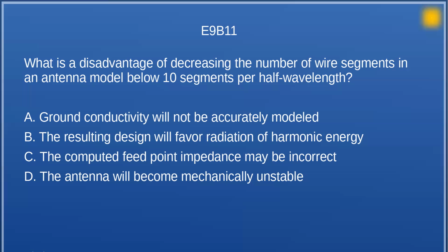Ideally, you want to make Z the same on both ends, and maybe X the same, and then do it over Y. And do wire 2 separated a little bit, the same kind of thing. Then connect it with a balun or transmission line and select a source to feed it with. And then you could actually do a plot of it.